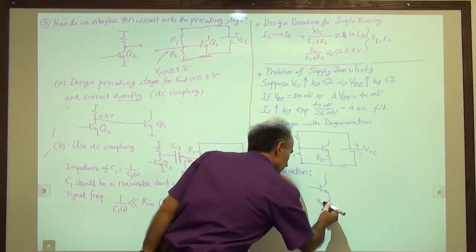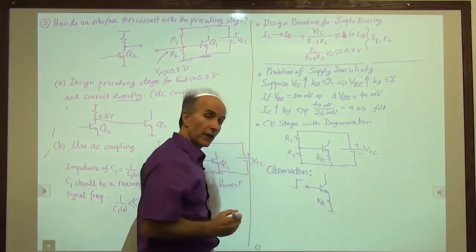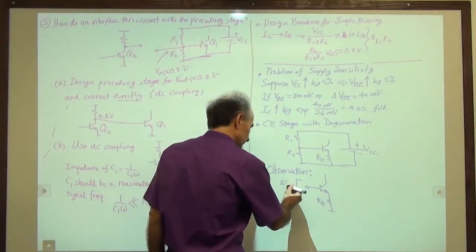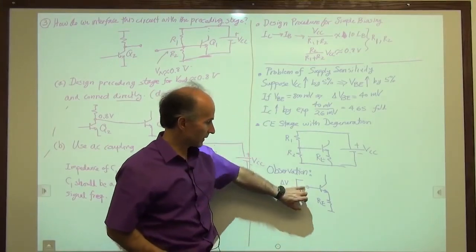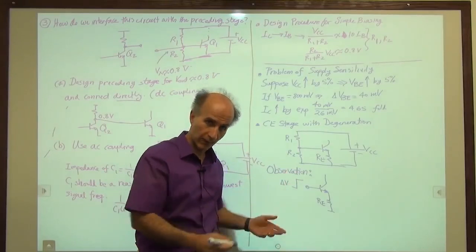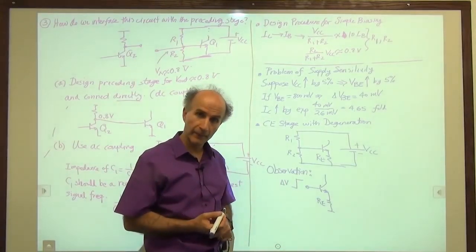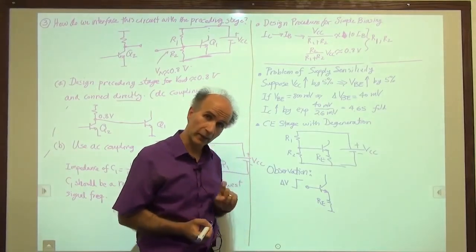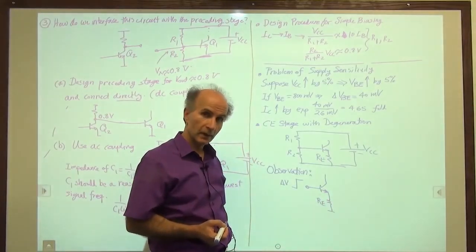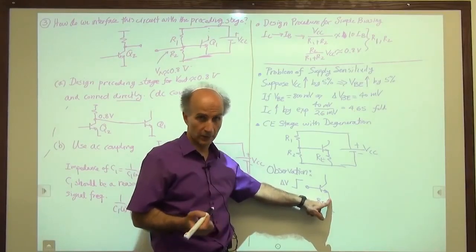We have a resistor here, and we come along and change the base voltage by a small amount, delta V. So let's say the base was sitting at some voltage, maybe 0.8 volts, 0.9 volts, 1 volt or something. And I changed it by a few millivolts. And the only question I want to answer right now is, what happens to the voltage at this point? Does this voltage go up, go down, or remain constant? That's what we would like to know.